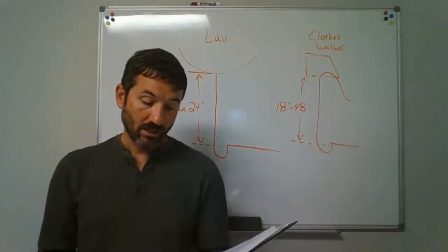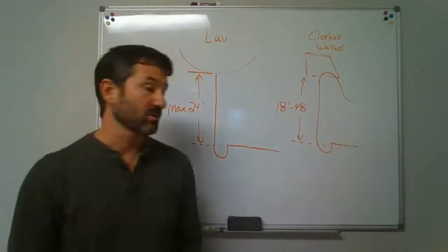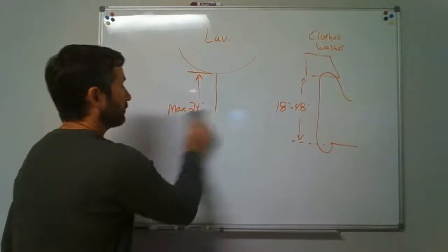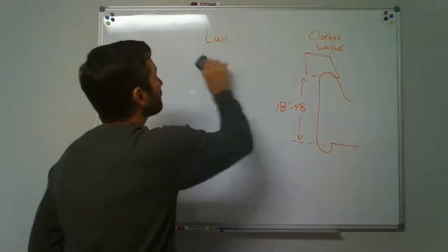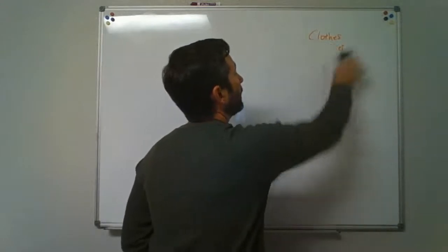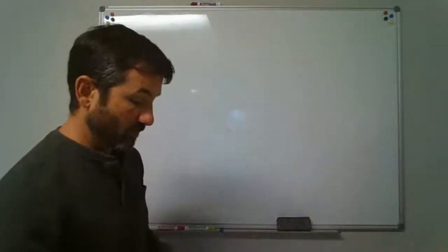We also said the maximum horizontal distance cannot exceed 30 inches. It will also tell us in a little bit that the maximum number of fixtures that we can have through one trap is 3 fixtures through one trap.